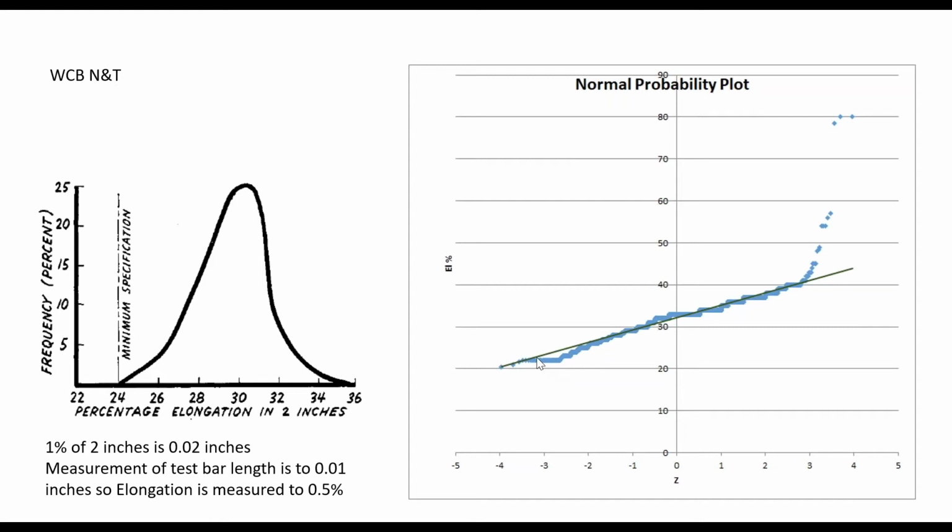And so what is a compliance bias? Compliance bias is when I fail to meet the specification and I look at that measurement or I remeasure it, and when I do, I know that I'm really close to meeting the specification.